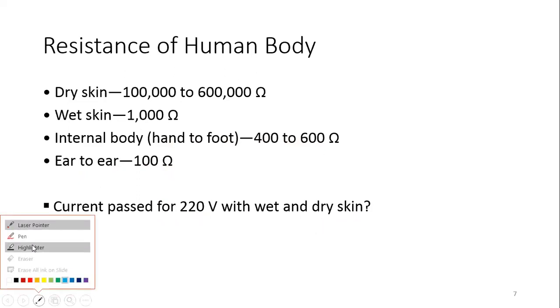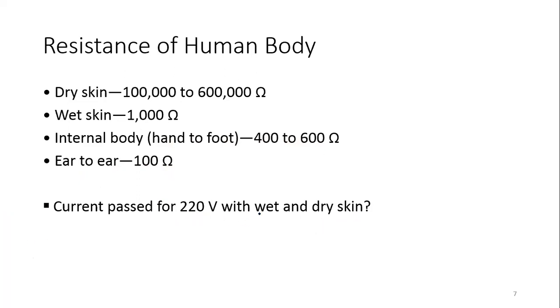With wet skin, simply using Ohm's law, you can see that it is 220 milliampere. And for dry skin, let's suppose we have 100K resistance.